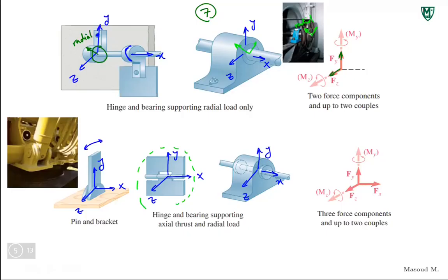You can't even have motion along the x-axis, as opposed to the previous one, where your shaft could still move along the x-axis because you probably didn't care about fixing it. But once you're at the end of a shaft, you have to make sure that the shaft is fixed there. Whatever system you have, a generator or an electric motor, you make sure that the stator is not sliding out and sliding in while it's moving.